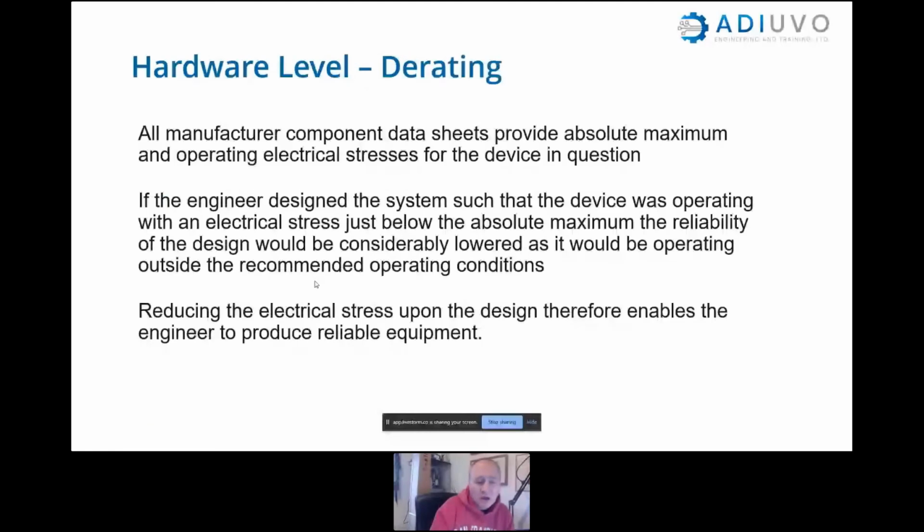One of the things we can do as well, and I'm not going to talk a lot about this, is some derating in our design. We can work with standards to reduce the electrical and thermal stresses on the components. If we can reduce those stresses, a much better system and much better reliability can be pulled through into our design.